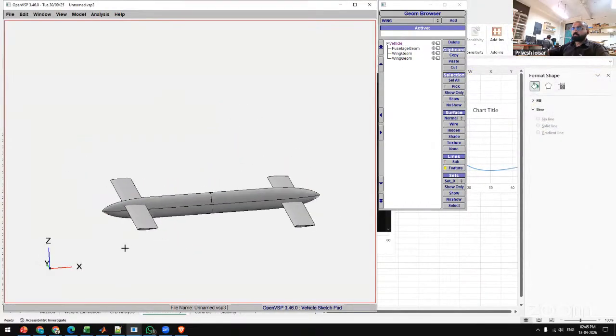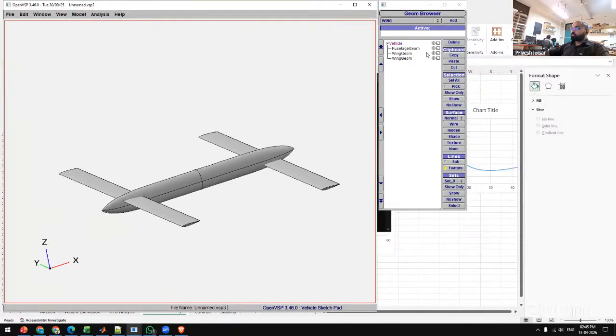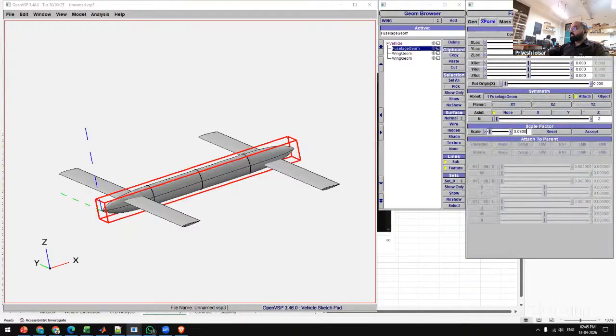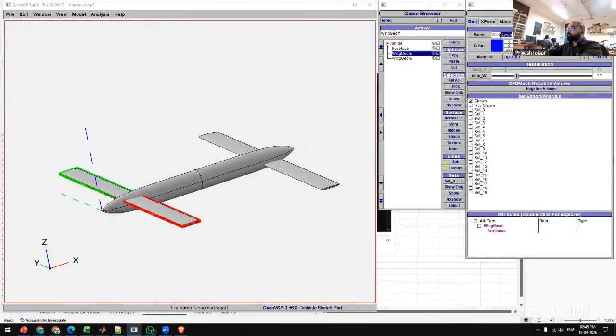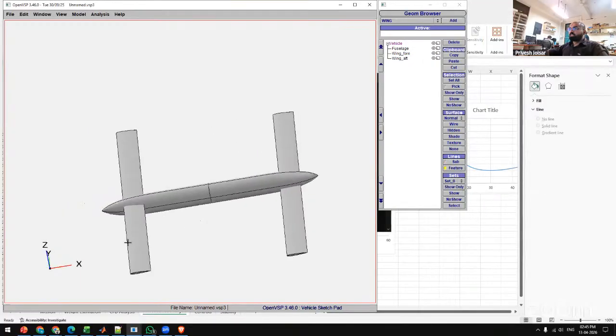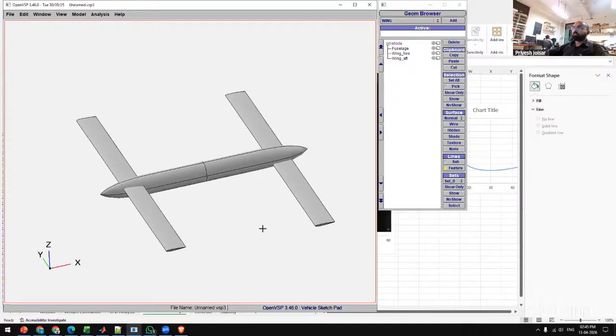Shade, let's say. Airfoil I will not change. Now this is the UAV. So I'll rename the fuselage. This will be wing forward. So wing fore. This will be my wing aft. Wing aft. Right. So we made this UAV. Now we will do the aerodynamic analysis. So I'll go to analysis, VSP Aero.